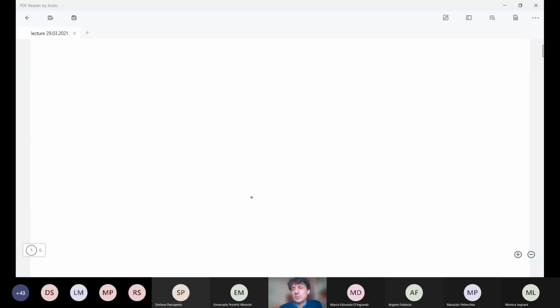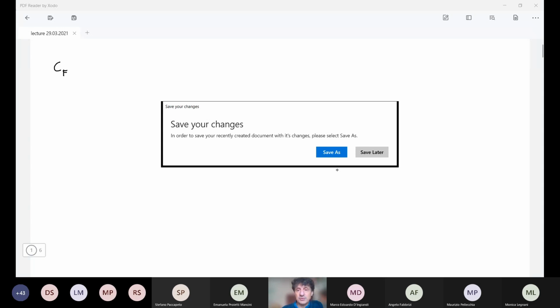So let's move towards a conclusion of the part addressing ideal rocket nozzles. About ideal nozzles, what we have seen, and I would just like to summarize here, is that the main performance parameter that measures the nozzle performance is our thrust coefficient.